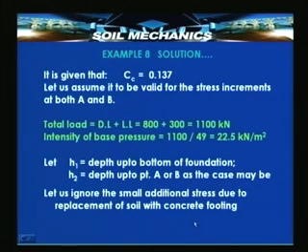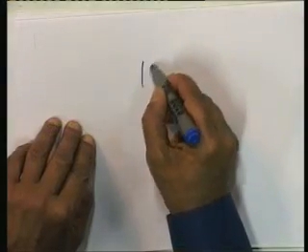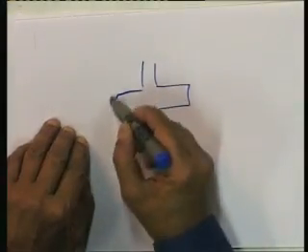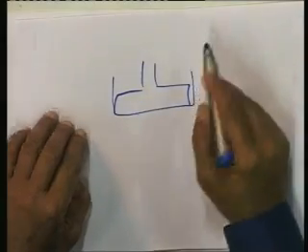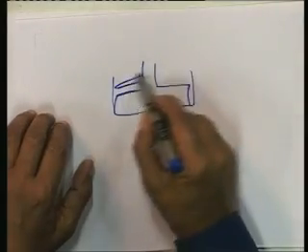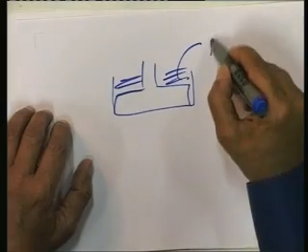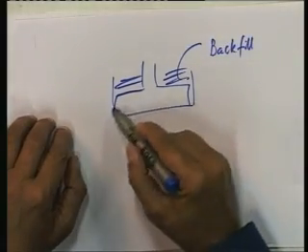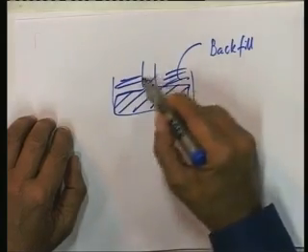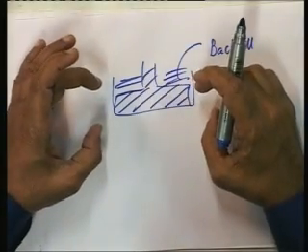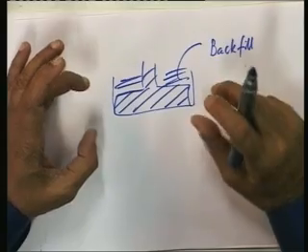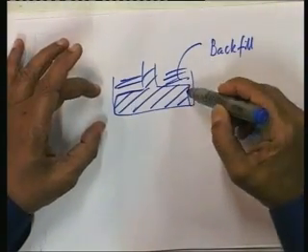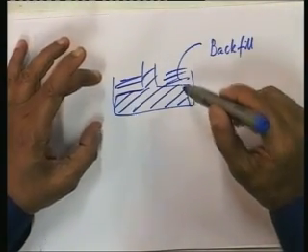Now, there is a subtle point which needs a brief explanation here. Actually, when you put the foundation, we will be removing some soil and replacing it with concrete, and then of course backfilling. This is backfill. That means in this portion, which is being occupied by the concrete foundation, since the unit weight of concrete is more than that of the soil, there is a small increase in the stress level.